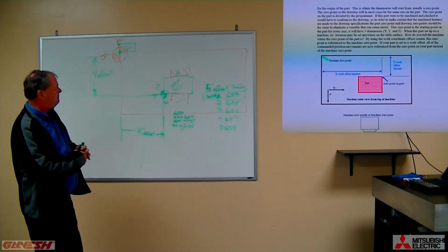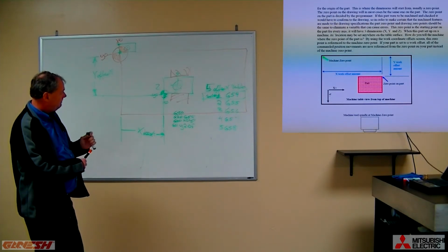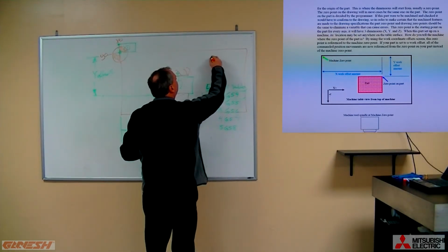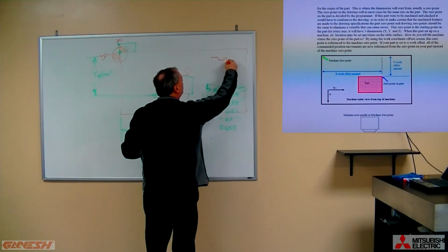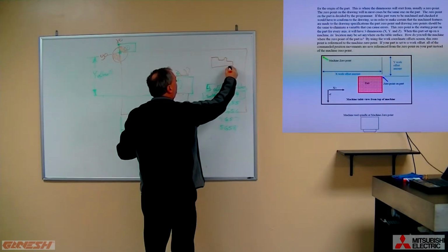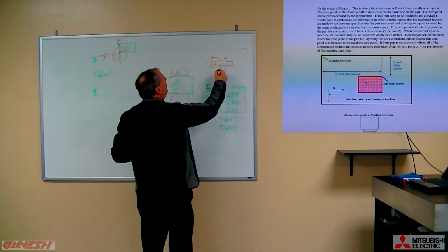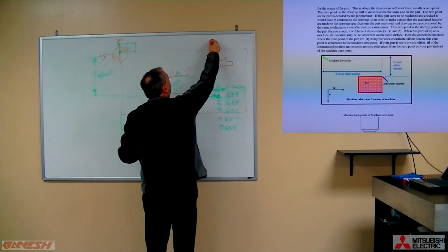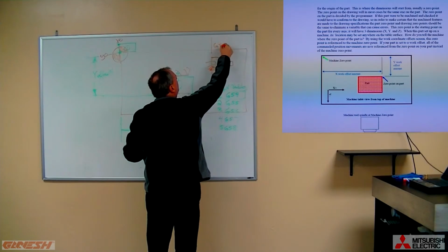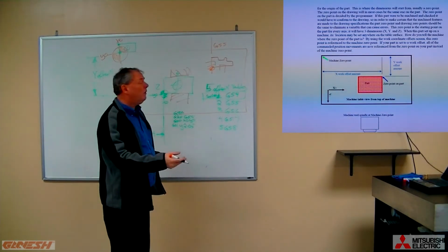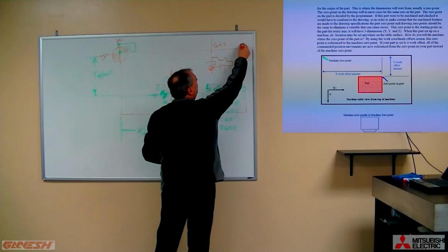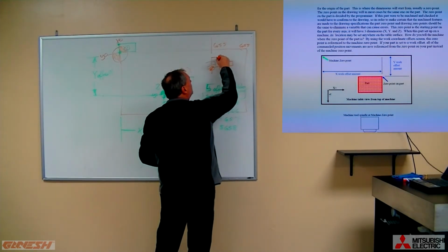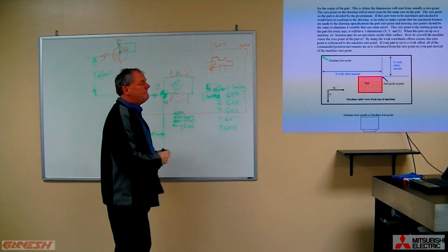This allows you to have multiple setups on one table. So if we had another setup of some other part that looked a little different, like the one you programmed before, and we said, okay, here is our origin, well, we can tell it this is the G55 work coordinate system, and we can have a whole different program that calls up G55 and then does all the movement that you just did when you proved out that program.